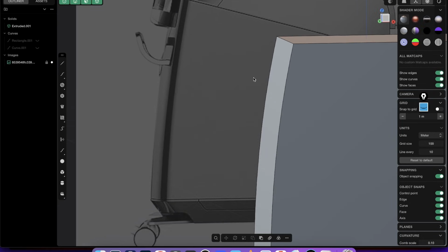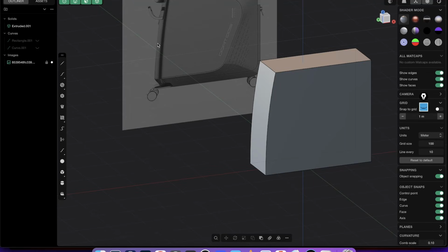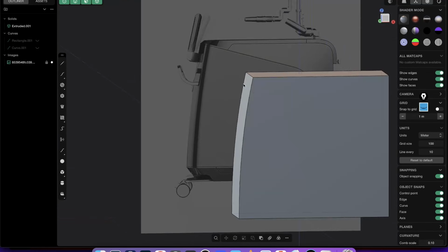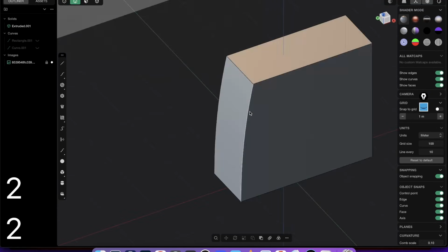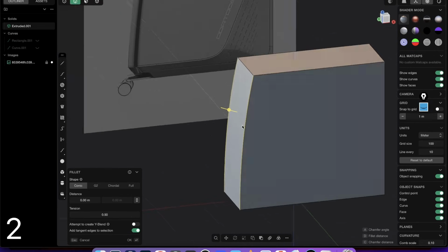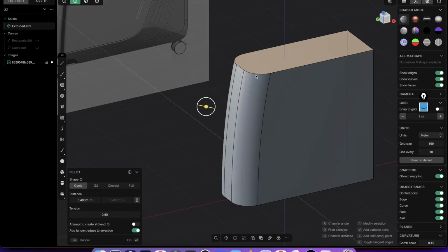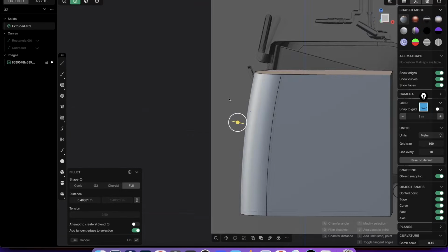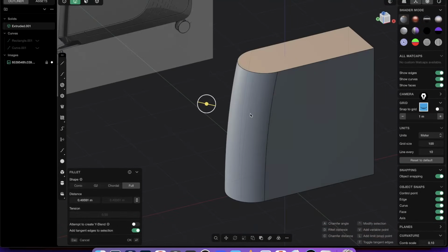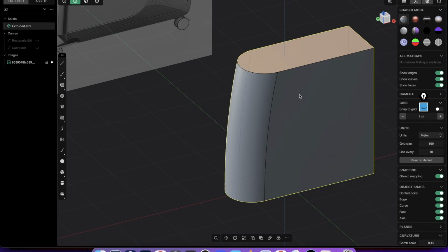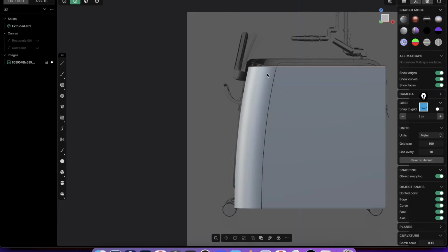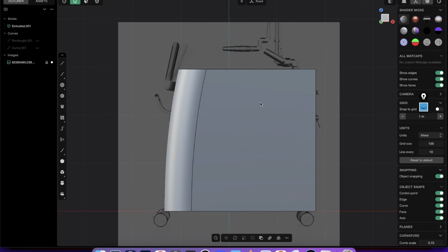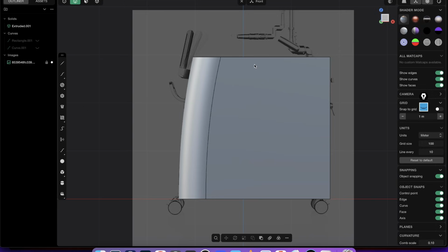the left. So very simple, it's kind of just a full fillet. And for that, you can just press 2, edge mode, and shift-click this edge. And now you drag that out, so you have a fillet, and just click here on full. And this way you have a perfect fillet. And this is exactly what we want. Right click, and perfect.